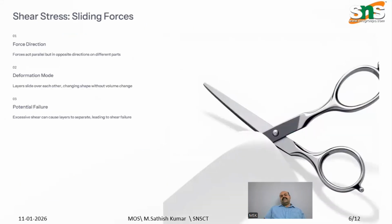So coming to the third and last type, shear stress, that is a sliding force. The force acts along parallel but in opposite directions on different parts. The deformation mode is that layers slide over each other, changing shape without volume change. Potential failure: excessive shear can cause layers to separate, leading to shear failure. The best example is scissors, where we have equal and opposite forces in opposite directions, and the shear failure happens on the cloth or any material which we cut using scissors.